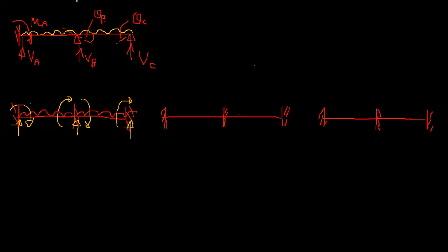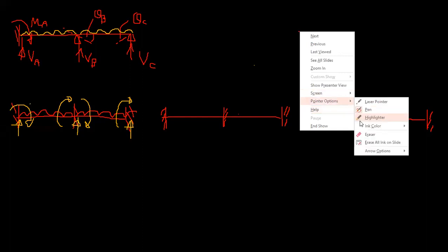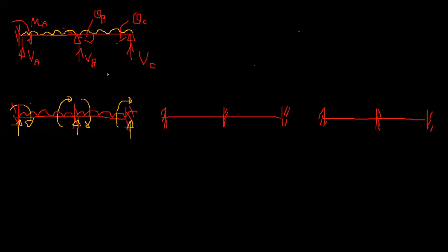So this was my original structure, right? So you have a deflected shape as I showed you earlier. So here theta 0, here will be theta B, and here theta C, right? So in the displacement method, we consider the equilibrium of the joints, right? Where we find theta B and theta C means here should be the redundant displacement, and here should be the second displacement, right?